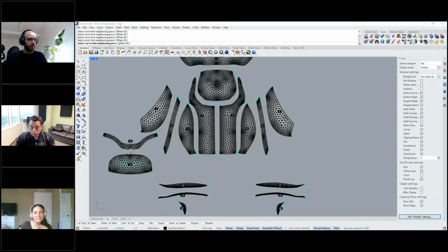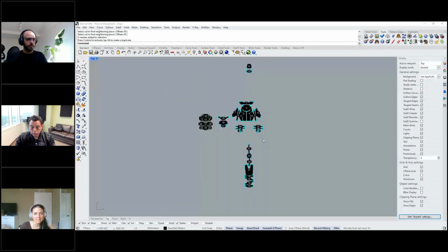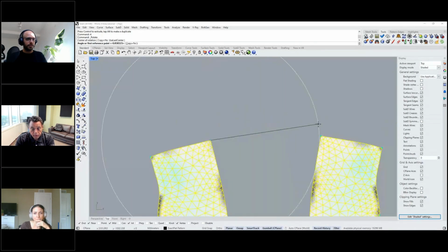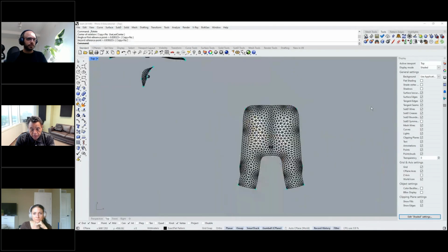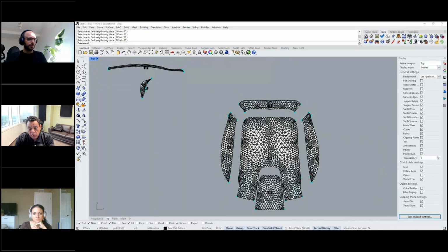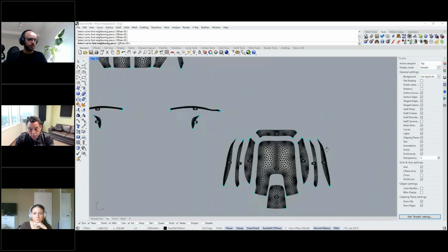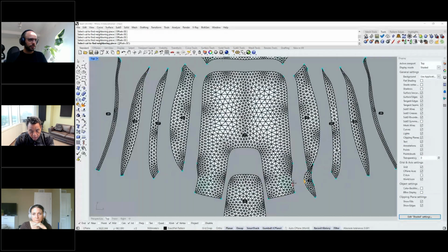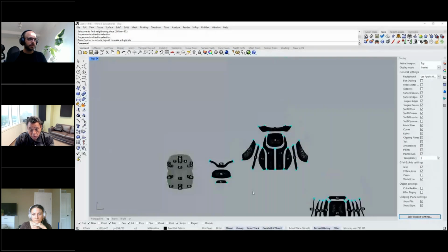Here you're clicking on the edges to bring in what's next to it. That's correct. The process that makes ExactFlat unique here is that all of the locations of those vertices, these are the intersecting points on the triangular polygons, have been indexed from 3D. And we maintain that indexing through to the 2D process. Even as the mesh elements are being redrawn and potentially the pattern geometries may be cut later on, all those locations are indexed.